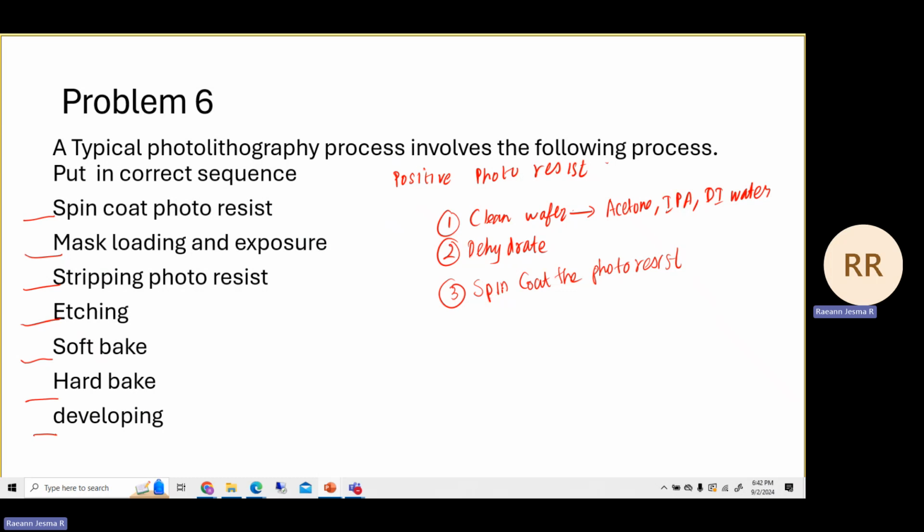If you look at various photoresists, some of them are AZ4562, AZ5214, S1813. In these photoresists, the last two digits will tell you how thick the photoresist is. So if it is 62, then the photoresist will be around 6.2 micrometer thick.